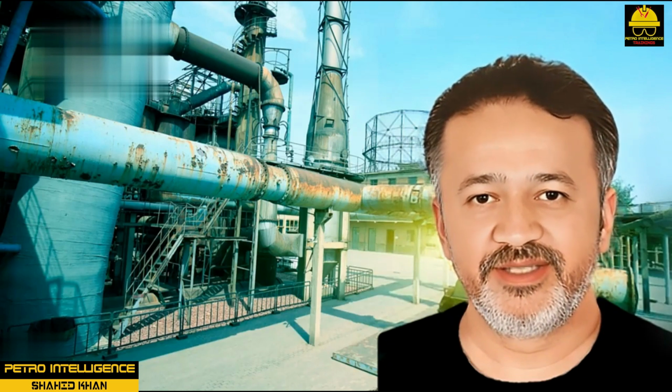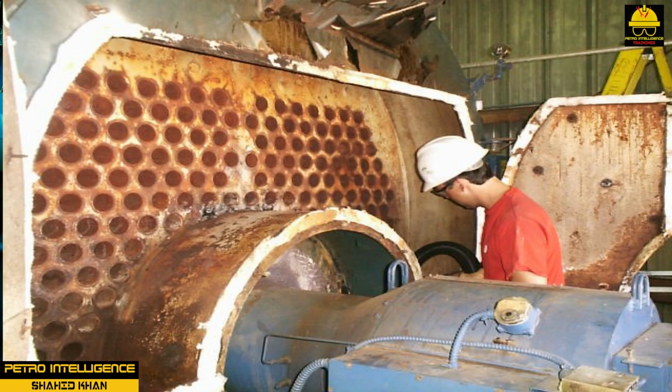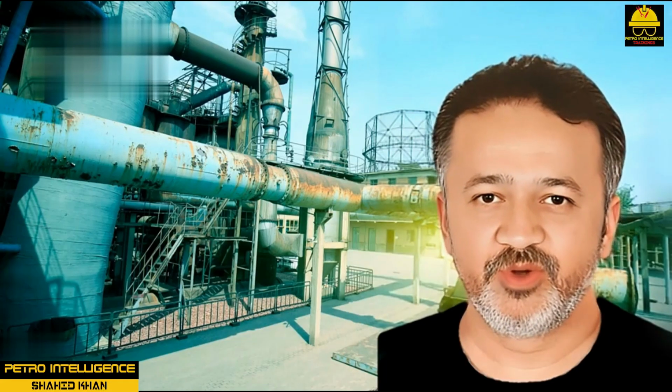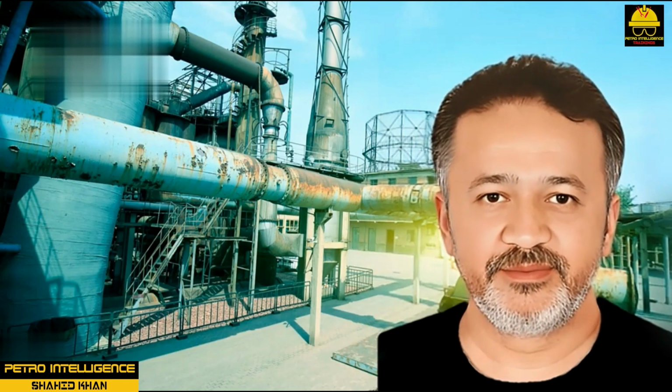Corrosion. The process of corrosion is a complex electrochemical reaction that can attack a large area or a small pinpoint area. Corrosion in a boiler is typically associated with the reaction of oxygen with a metal. However, pH, a measure of acidity, stress, chemical compounds, and other factors can contribute to corrosion. Corrosion may occur when the boiler or boiler feed water has excess acidity or alkalinity, high levels of oxygen and carbon dioxide, high temperature, stress, or high levels of ammonia or sulfur-bearing gases.